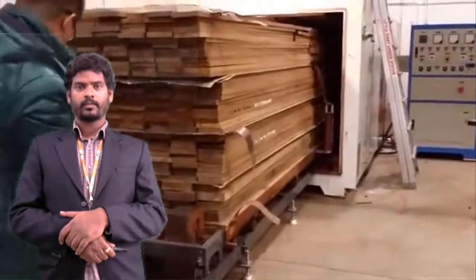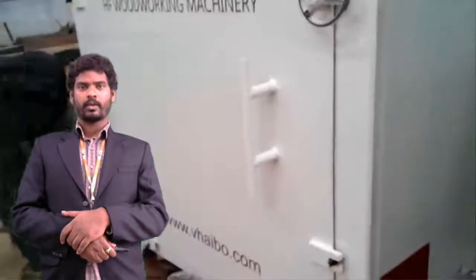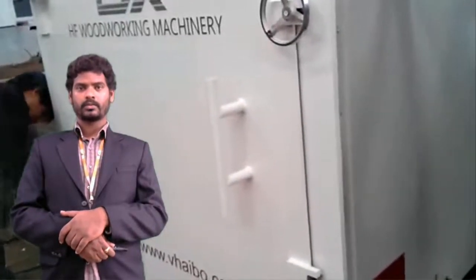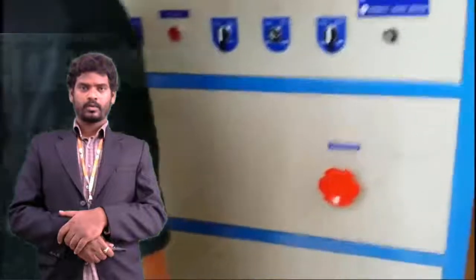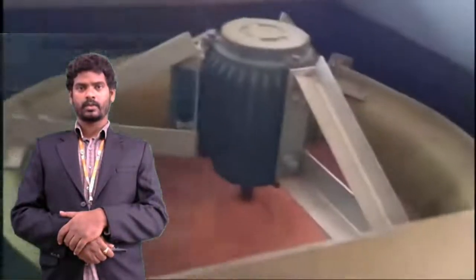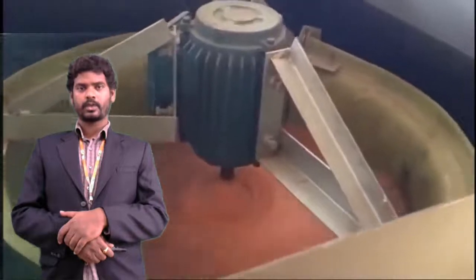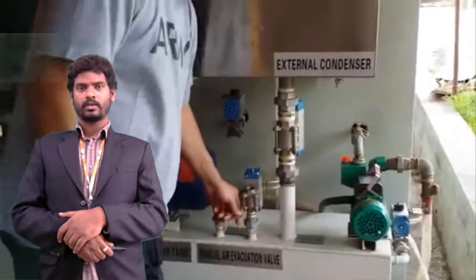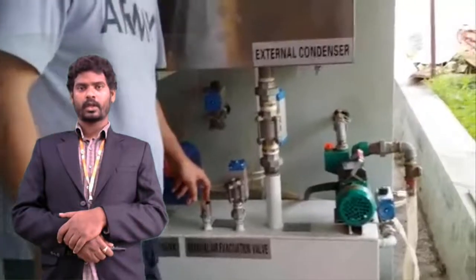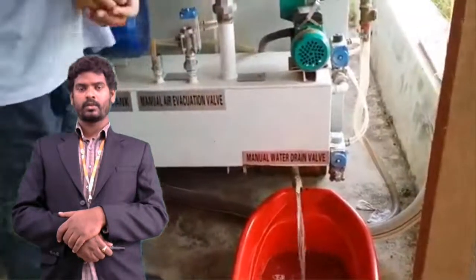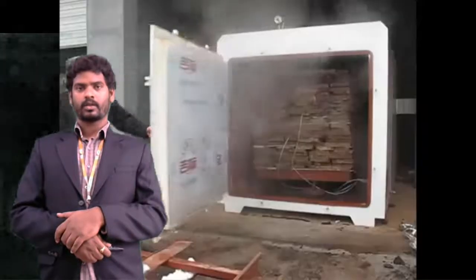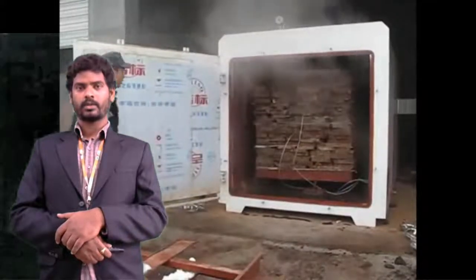This method of seasoning works on the principle that heat is produced when pure conductors are placed in the field of high frequency. The wooden planks are made to pass through an induction coil producing high frequency. Due to an induction effect, moisture contained in the wood is directly, quickly removed. This method of drying is employed in the plywood manufacturing process.